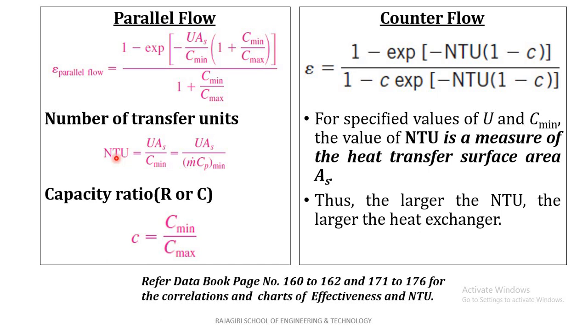If NTU increases, the area of the heat exchanger also increases. That's why earlier I told that the value of NTU is a measure of the heat transfer surface area or size of the heat exchanger. The larger the NTU, the larger the heat exchanger.